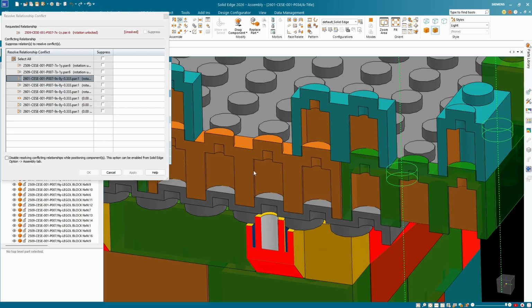So that's holding that orange block in position relative to our base plate. But we want to move that along by 2 pegs. So that relationship there definitely isn't helping us. So I'm just going to hit suppress for that. And we look at the next one.